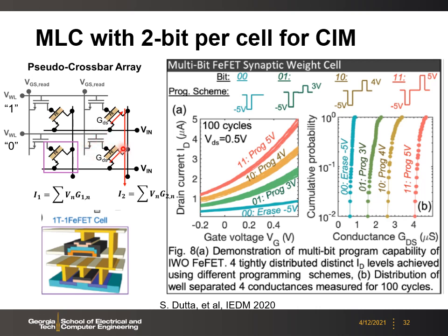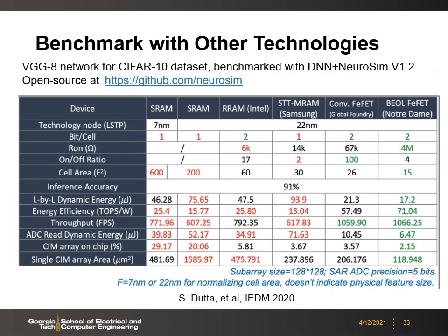To summarize here, we need 1 regular transistor and 1 FeFET. Therefore, the 3D folded back-of-line FeFET bit cell is perfectly suitable for this application. Lastly, we show a benchmark at the system level to review the benefits of using the FeFET, especially back-of-line FeFET, for the neural network acceleration.